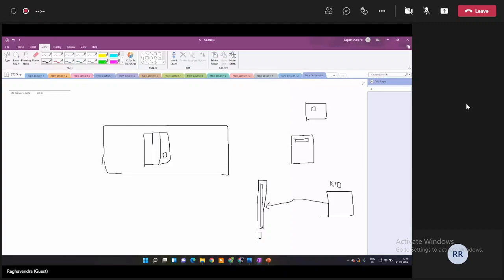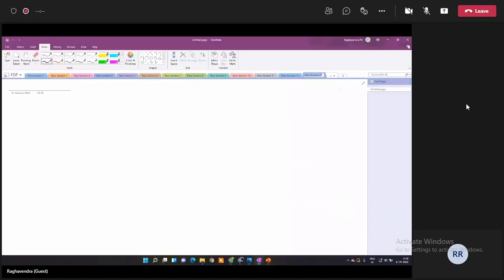Now, I told you that there are two things I meant when I said synchronization. One of them, I just showed you what it means. It means that you give some reference to your USRP so that both your carrier frequency that you generate from the local oscillator as well as the ADC, DAC sampling that you do is correct. Now, there is another type of synchronization that is required, which you may be familiar with,